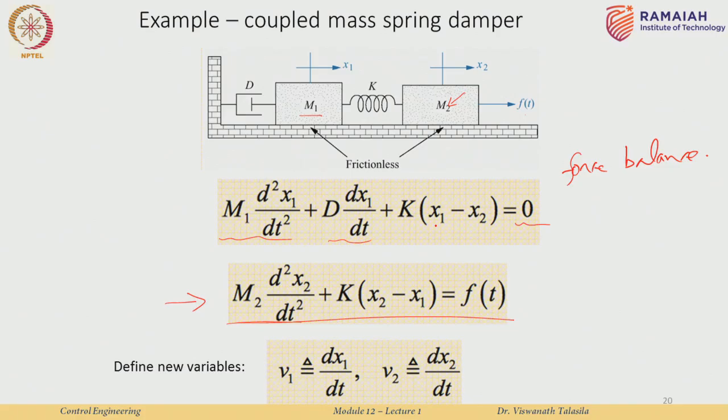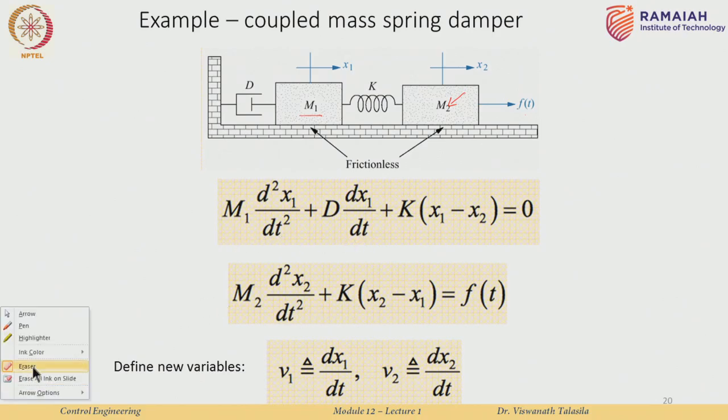So, as we did before, we want to write down the state space model of the system. So, the first thing we need to do is to identify the states, right. The way that we are going to do it, as we did for the original mass spring damper system, is we identify x1 as basically the position x1 itself. So, x1 of t is equal to x1 itself.